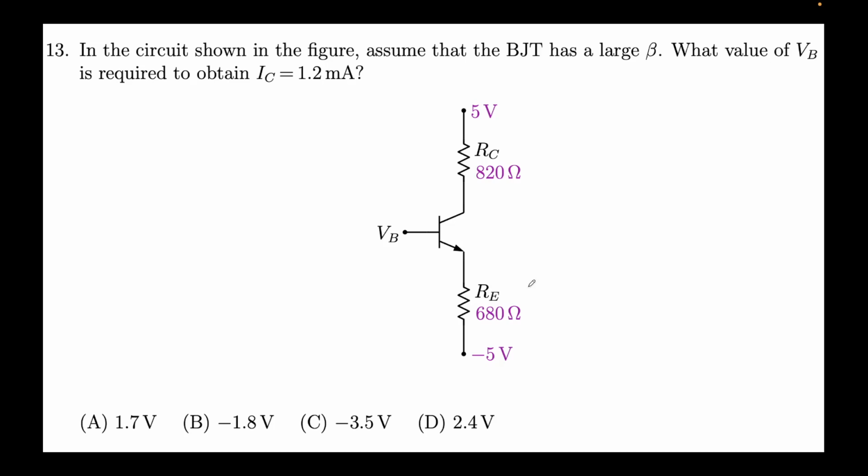So now we'll move ahead to the final problem set. First of all, as I always say, just try to identify the BJT. If the arrow is coming out of the vertical line, this means it's an NPN BJT. This is your N, the collector, this is P, this is N. The arrow side is always the emitter.